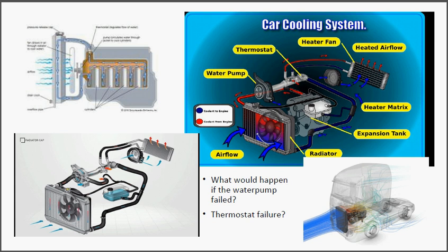It wasn't overheating, but the temperature was really, really low. When I turned on the heater, it was just lukewarm air coming out, not hot air. So the car worked, but wasn't quite as economical, and that would be the other extreme. The thermostat is open all the time, and then you don't get the temperature you're actually aiming for, which is close to 100 degrees for your car. Okay, let's move on. Go to the next slide.